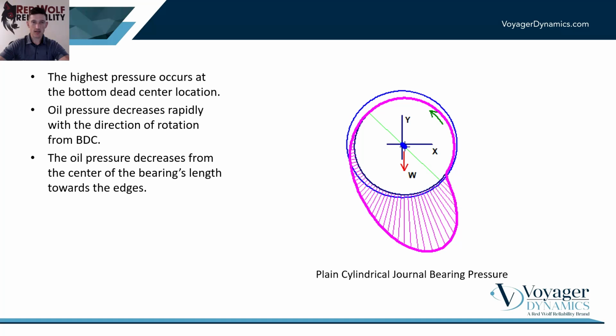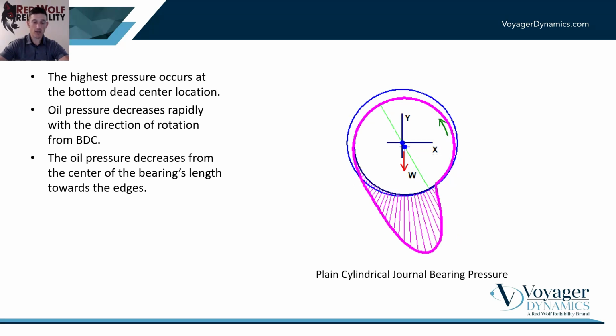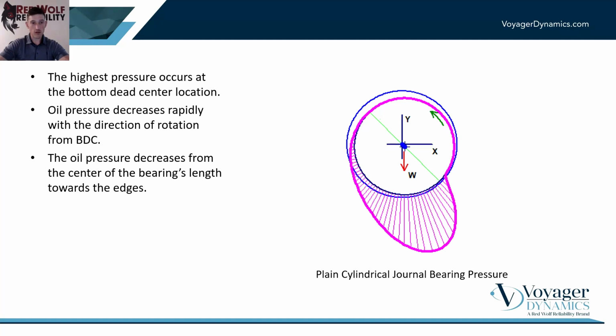It's important to discuss the oil pressure, right, where you have high oil pressure. That's what transmits the load from the rotor to the bearing housing. And so we want to be in that location of highest oil pressure. And that oil pressure follows the load.